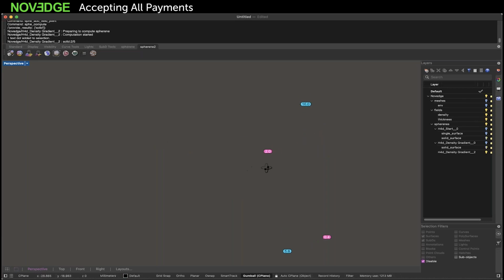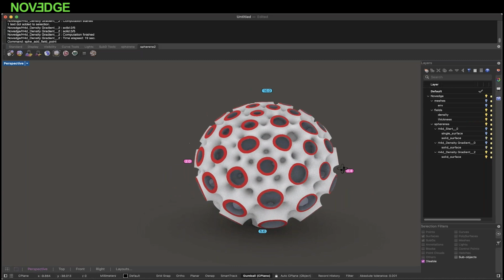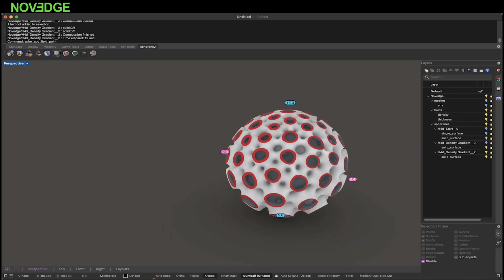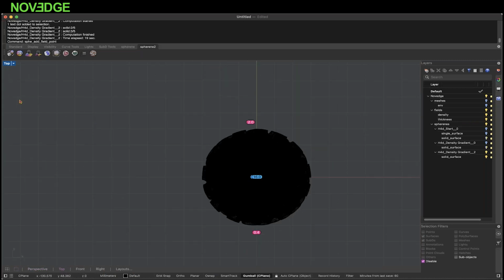So now let's change another field type. Let's add the surface bias so that we can compare what's happening. So, sorry, now we got the result back. So this one changes from 0.4 and obviously to 2 millimeters. Very cool. Now let's add this so-called surface bias. So another field point, surface bias, and make this 0.98.